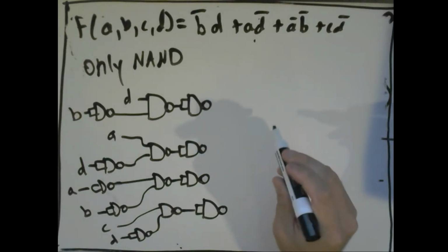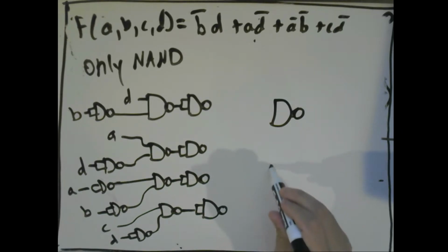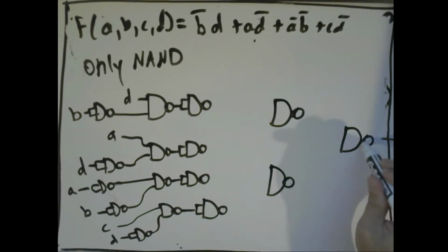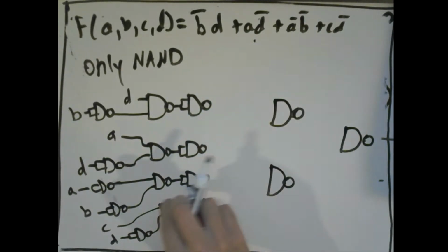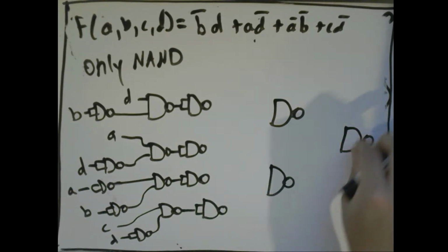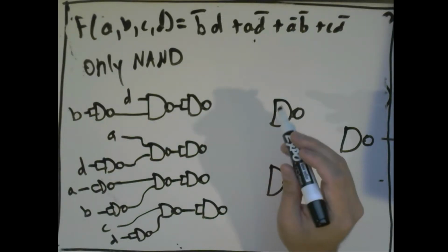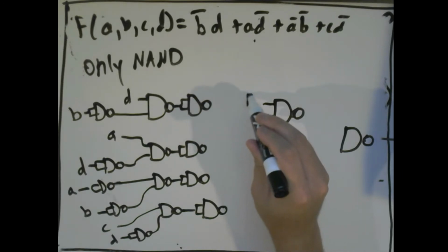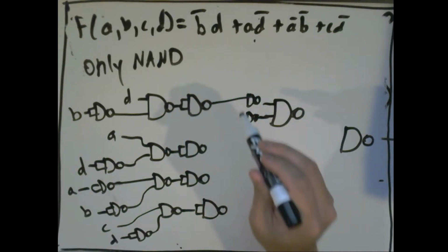How we do that is we take the NAND gate, and we need one stage and then a last stage. This part will OR these two together, this part will OR these two together, and then this will finally OR the last part together. So what we do is we want to invert the inputs, and then we want to connect these together like this.